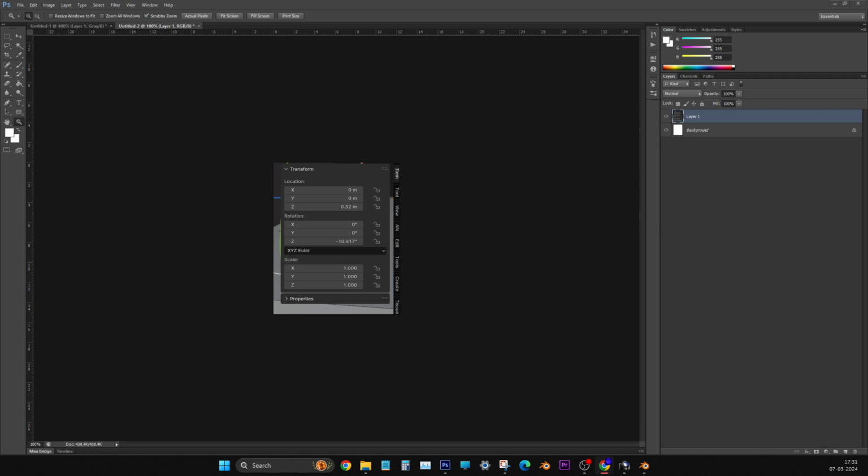Now you see both the vertices are selected. Now press M on the keyboard. M for merge. Merge by distance, last option. Now go to merge by distance. The settings are there on the left side. It will show the settings always, anything you do, open it. Now go to the distance and type 0.01. Okay. 0.01.